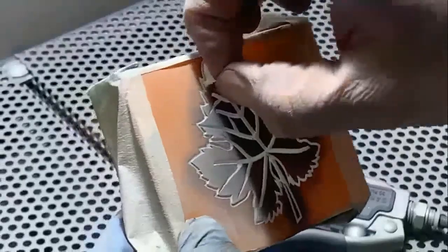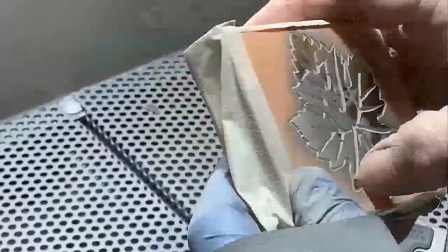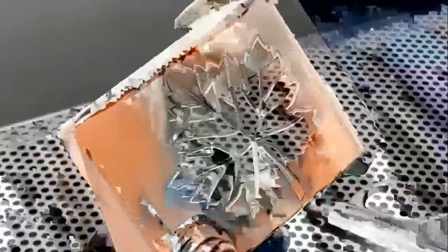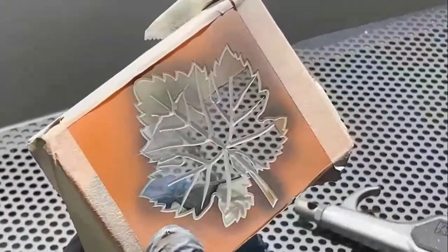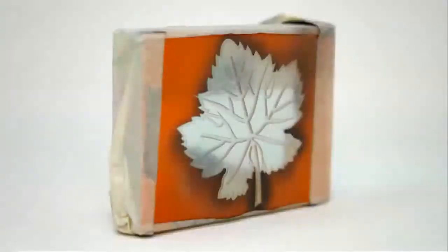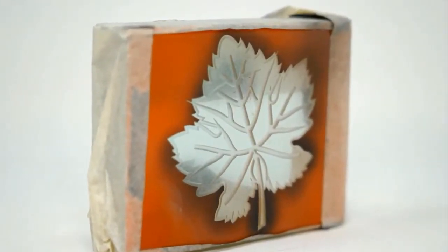So here you'll see my hands in action, peeling away the stencil. And this is how we do a 2-step or 2-stage carve. So after removal, you're going to shoot your abrasive at the piece. Now, in this image, you're going to notice the face is not going to be pure white. It's kind of a grayish or shade look.